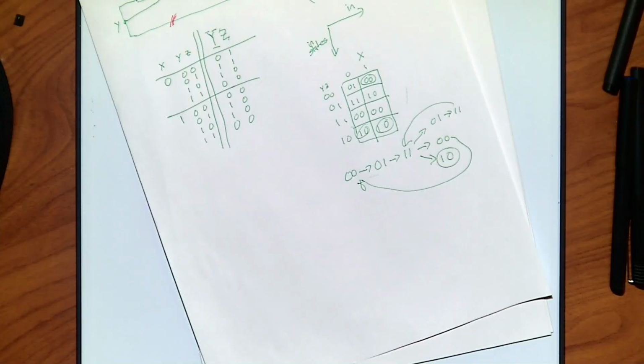So I could design my system by building a Karnaugh map where I like the properties, much like we built truth tables before. So we could have some user inputs, and we're going to talk about how we can build these methods in a sec. But as just a general idea, I could take whatever my user wanted, build a Karnaugh map, put the states on the rows, put the inputs on the columns, and I could go in and label them. Where do I want stable states? Where do I want transitions? Things of this sort. And make sure that there are no critical races.